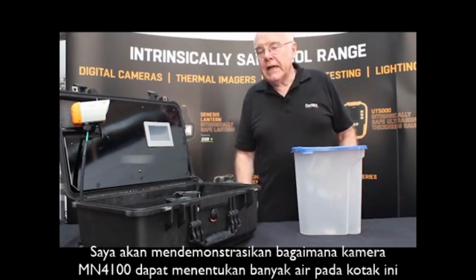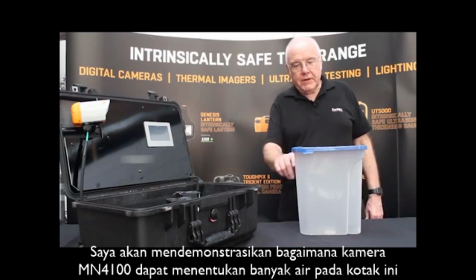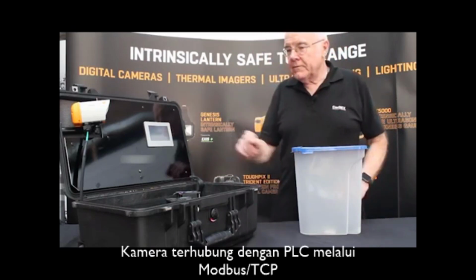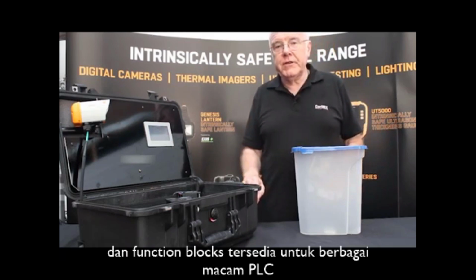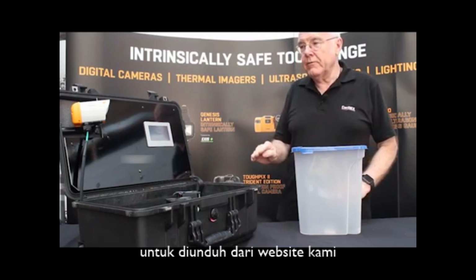We're going to demonstrate how our MN4100 camera can be used to determine the level of a liquid in this container. The camera communicates with the PLC via Modbus TCP, and function blocks are available for all the major manufacturers of PLCs to download from our website.